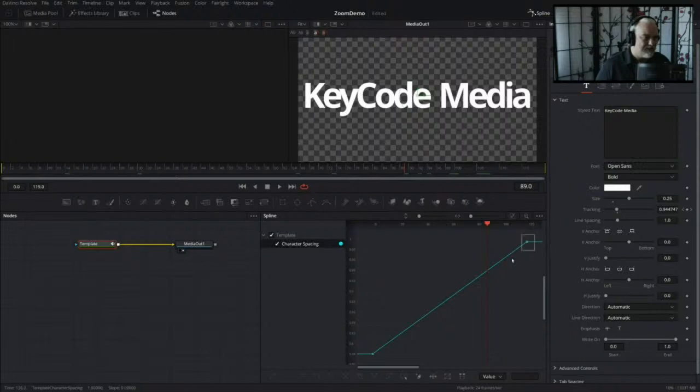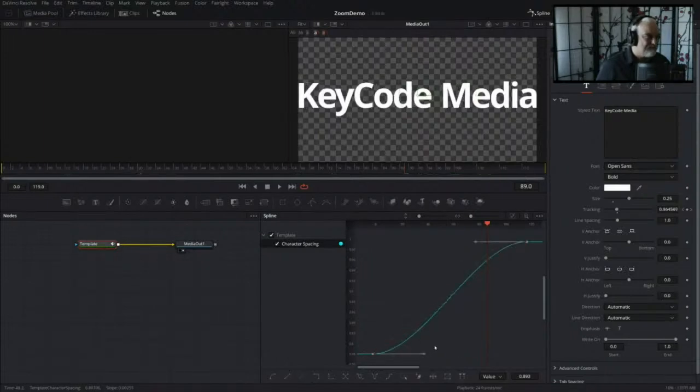So here are my keyframes, but plotted on the spline graph, and you can see now it's a linear acceleration. So I will select both of those points, and you see now that there are Bezier handles to break off. With the smooth function, which is Shift S to smooth, or in this case I'm going to flatten the curve out and put the handles here. I'm going to hit F to flatten them. Very simply, now I've got a nice ramp.